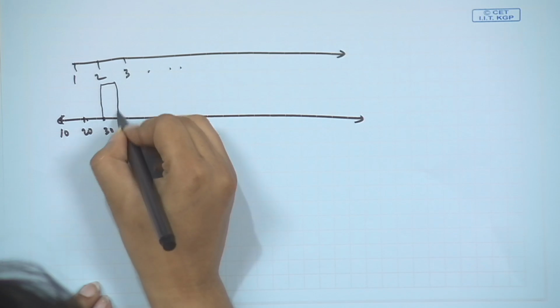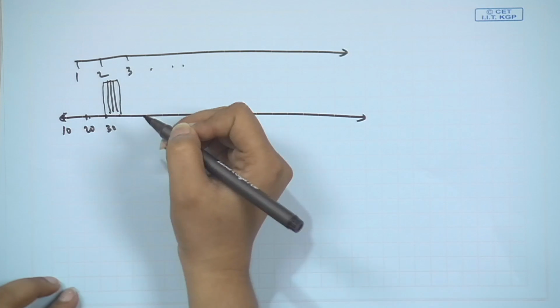In a human ear, as I said, different frequencies activate different parts, and that is why they create different levels of vibrations. So for sound quality calculation, we represent the linear frequency scale as a bark scale, and the individual bands within this bark scale are called critical bands. Within an individual band, the definition is that these are those frequencies which activate the same part of the membrane of the human ear, the basilar membrane. So the individual frequencies within this activate the same part, so obviously their response will be similar.